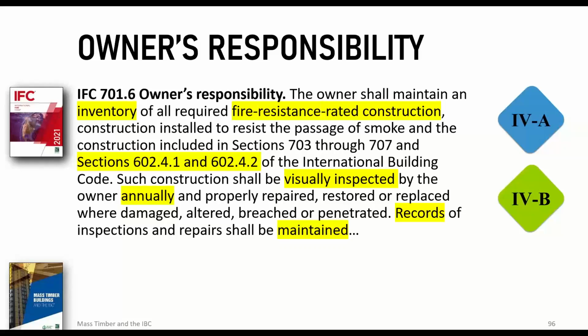Okay. The International Fire Code had items for which the owner is responsible, the non-combustible protection and other requirements that are required in Type 4A and Type 4B construction. Construction materials currently required for buildings of similar heights and areas will not contribute to the fuel load in the manner that mass timber could. As such, tall mass timber buildings are required to include specific active and passive fire protection features to protect the occupants and structure from fire.